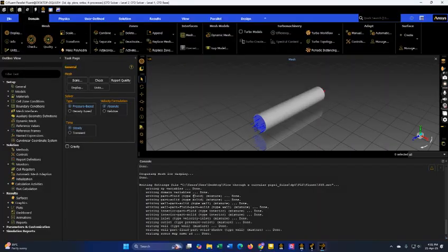So go to the fluid, and now the general settings are all okay. Now we have to choose pressure based, because our velocity and density will not change in this flow. If our density would change, that would mean we are dealing with a compressible flow, and then we would choose the density based option. For now, we should use pressure based conditions, and the time is steady as well. That means the velocity will be steady along the time. That's it.